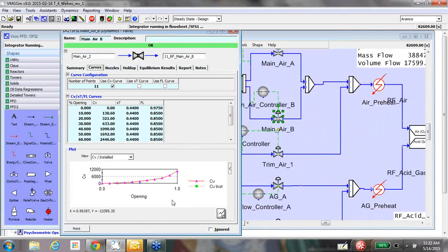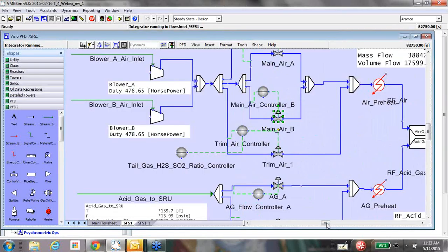So it creates a really high fidelity model in terms of the behavior of the valves, and it also helps us to come close to the real tuning parameters, which they really want to know, like if they have turned down or turned up scenarios, what would be the ballpark range for the tuning parameters, so they don't have to wander around too much while they go for those changes.